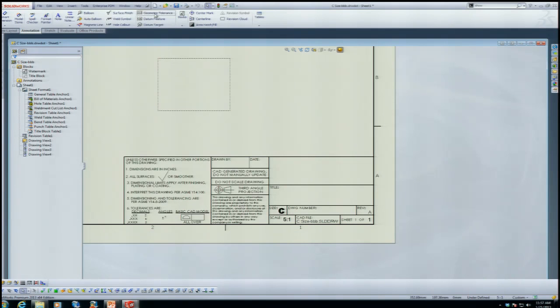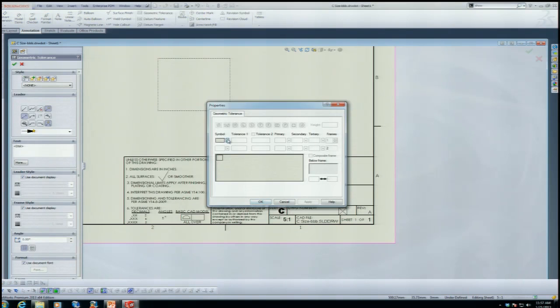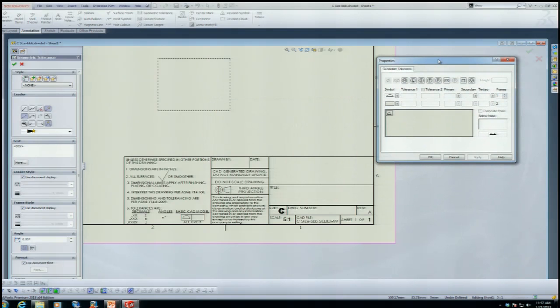One place you can add a GD&T is on your drawing. And I guess maybe I should discuss one of the reasons why you might want to add a GD&T callout to your drawing template real quick. There is a push in the industry to start relying on the solid models more frequently for design, for building parts. When you send out a part to a vendor, a lot of times they're using the actual solid model itself directly.